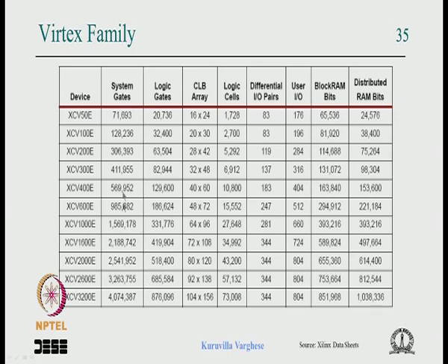Maybe you can use it to decide between devices within a family. But there is no point in comparing the system gates of one family with another, or one chip from one vendor with another chip from another vendor. It doesn't make much sense, and one shouldn't choose FPGAs depending on these system gates and logic gates, though it is an indication of the complexity.